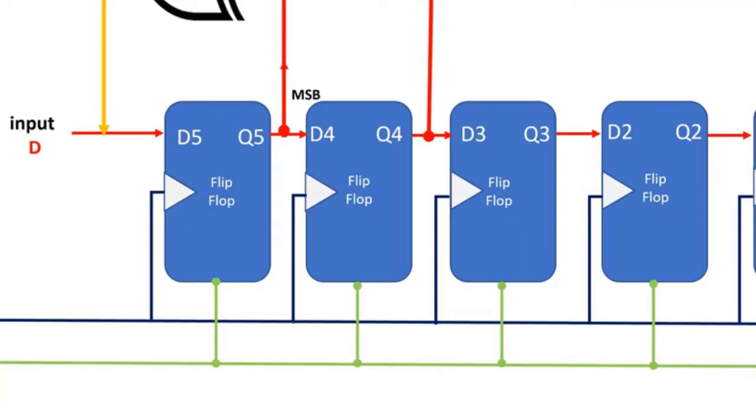Since 6 bits create random numbers in the range from 0 to 63, no random number should be repeated until all those 63 outcomes have taken place, and therefore we tap the 5th and the 6th bit of the D flip-flops in order to avoid that.